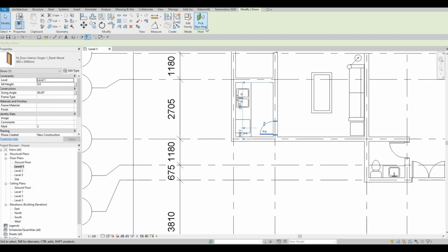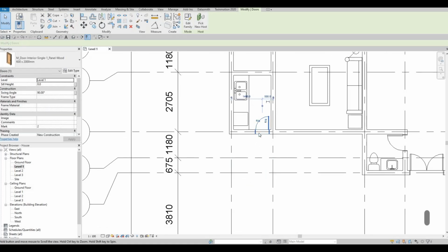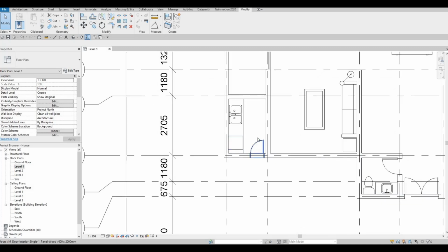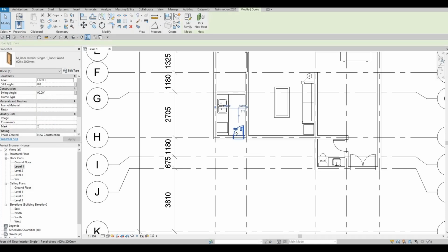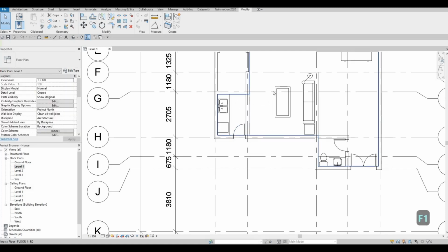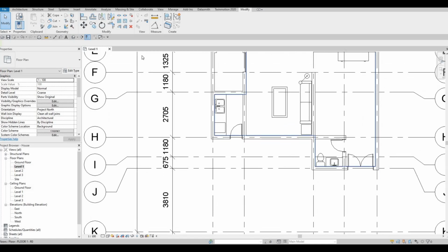And now what I'm going to do is add this interior door, going from the outside so that we have enough space. So what you do in order to relocate this is to pick new host and then press spacebar to change orientation, and then just select this area. So that's how easy it is to relocate the door. Here, instead of 600, I'm gonna go to drop down and make it 700 as well, similar to this, because we have enough space now in order to access this.